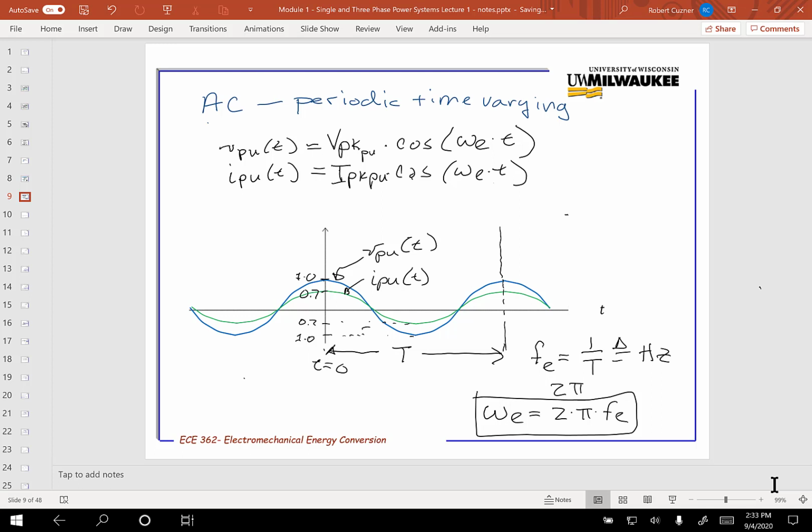And so obviously we've been talking about a resistive system, so it's applied across a resistor R. And so we would know that I peak equals V peak, now that I'm showing this in real units, divided by the R. So I peak in amperes is V peak in volts divided by R. Okay, so we have this established.